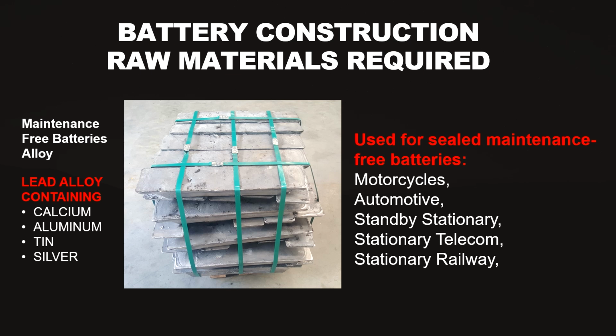So these batteries are also known as SMF, that is sealed maintenance free, and they are also referred to at times as VRLA, that is valve regulated lead acid batteries. In these batteries, there is no possibility of topping up with water throughout the battery's entire life. The vent plugs are sealed, preventing any maintenance.